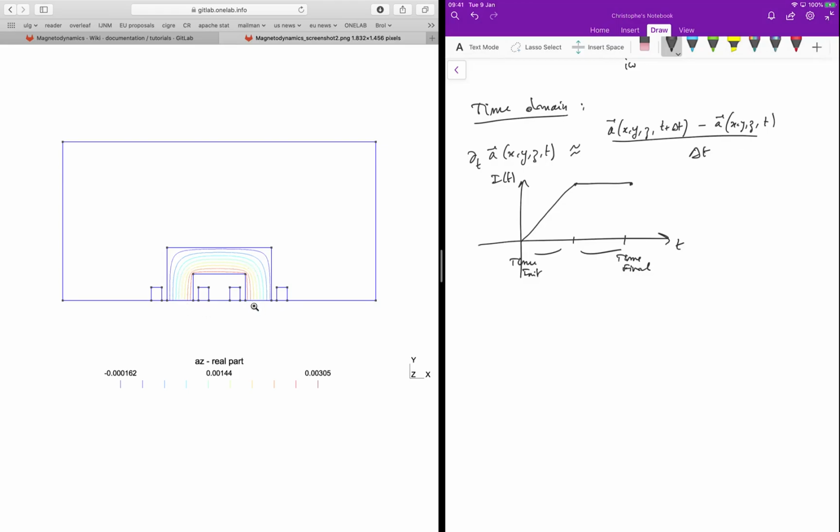And here you see in the middle you have a magnetic core. And then you have a primary winding on the left and a secondary winding on the right. The idea would be, if I impose here a current that varies in time, since the flux that is channeled through the magnetic circuit is time varying, then I'll see in here a variation of the flux in time, which will lead to electromotive forces taking place in the secondary winding. And if I close my windings on a load, I will have a current.